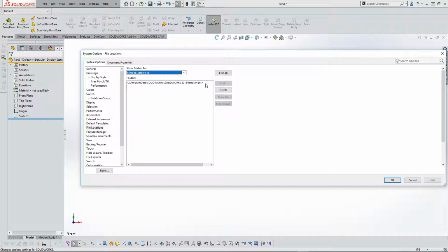Not many of us know how to do that, and so sometimes we just say, all right, SOLIDWORKS says to install, and remove the old version in the installation manager and just plop in this new one. So many times when you do that, these sort of things do happen. Or if you have multiple versions of SOLIDWORKS on your computer, this can happen as well.